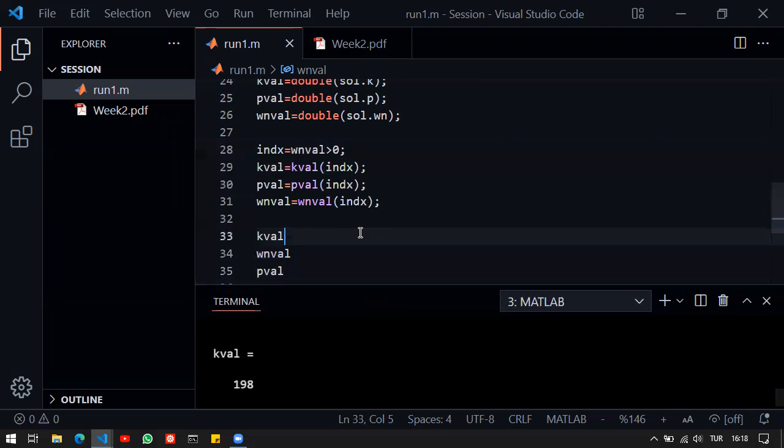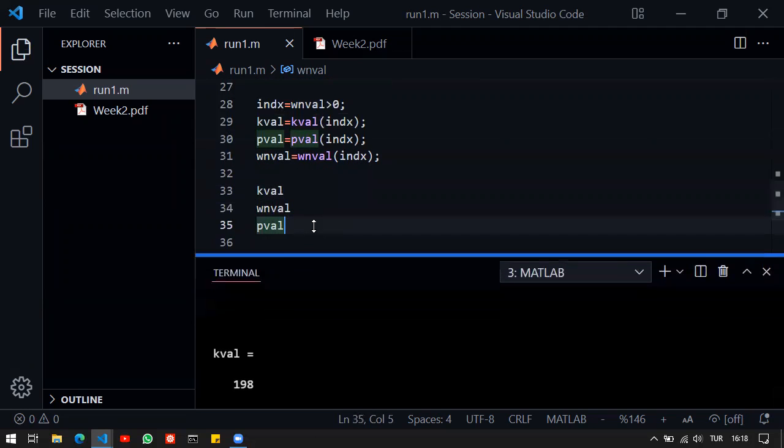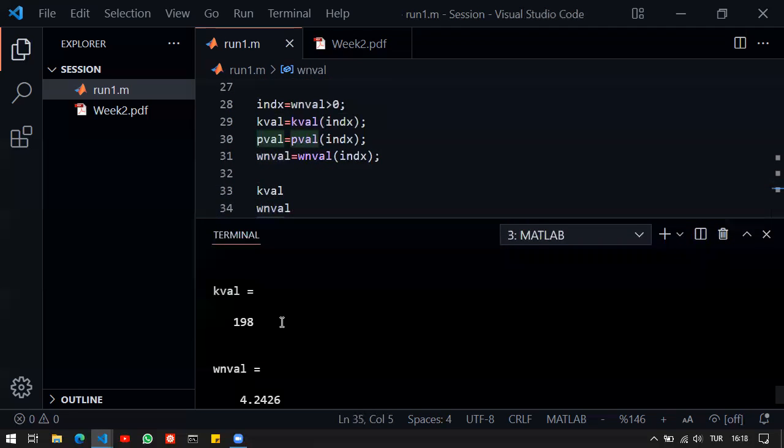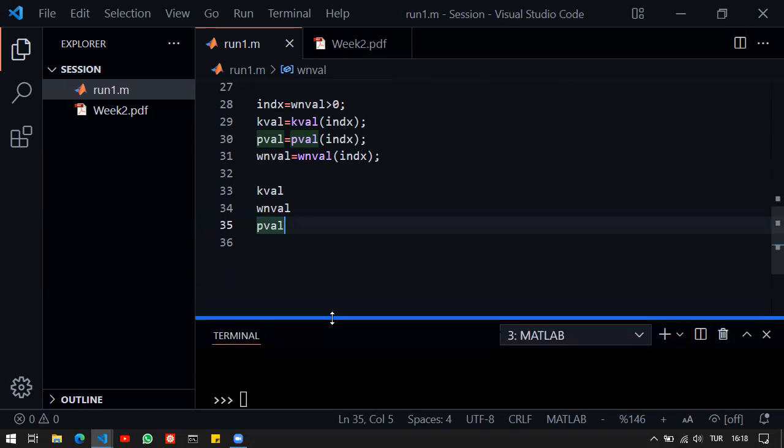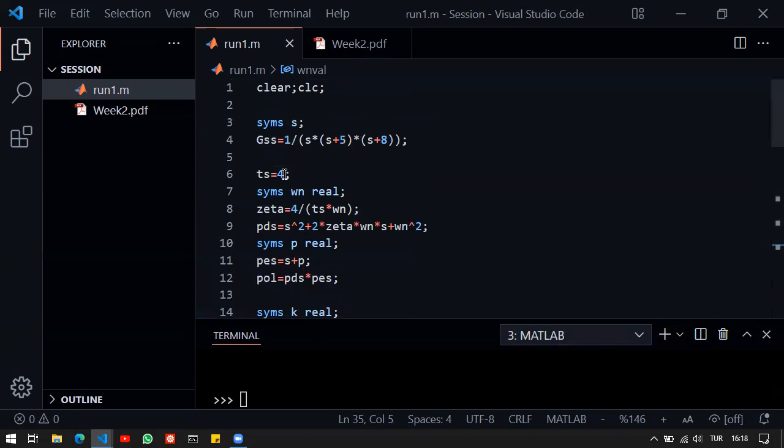Now, at this point, you may say that I'm basically done, we've finished, we've designed the p-type controller, and that's it. Unfortunately, it's not. If you have a certain design, then you should verify if the design really works. Our assumption was that the requirement is equal to 4, so the settling time in the closed loop should be equal to 4. We have to use the controller, use the transfer function, calculate the closed loop, apply a step type input to it, and see what the transient looks like.